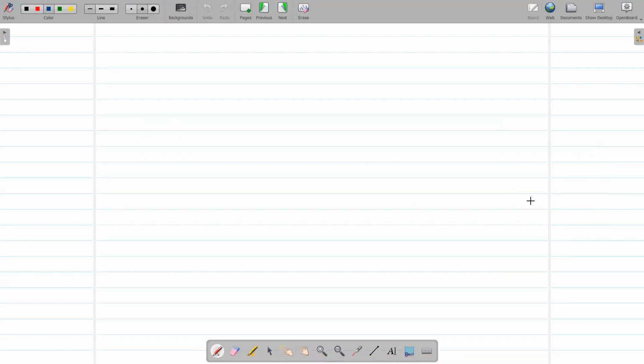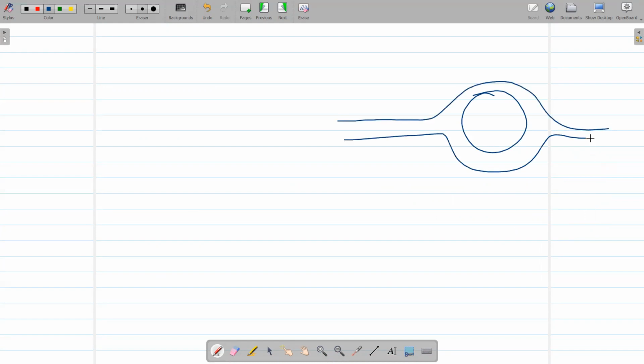So, going to the non-lifting flow over a cylinder, we know that the velocity on the surface of the cylinder, let's say the cylinder has a radius r, the r directional velocity is 0 on the surface of the cylinder, which is understandable because you cannot have perpendicular velocities.